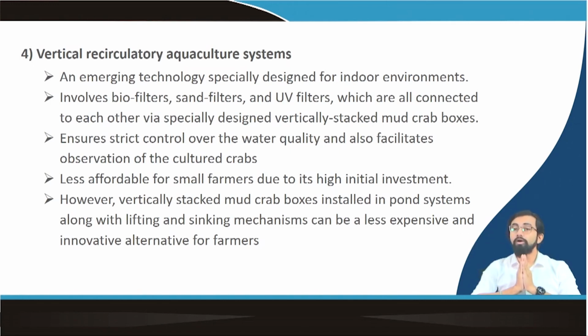Why are biofilters used? Biofilters are mainly used to get rid of the carbonaceous and nitrogenous compounds, which are very high in these culture procedures and farming techniques. So, to remove the carbonaceous and nitrogenous species, we go for biofilters, where microorganisms are artificially grown, which consume the nitrogen and carbon from the wastewater and develop their biomass. The water coming out of the biofilter is free of that nitrogen. It is not completely free, but they can reduce the pollutant load.